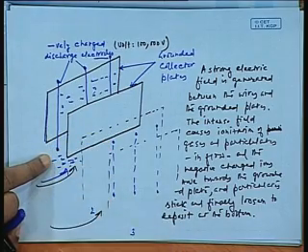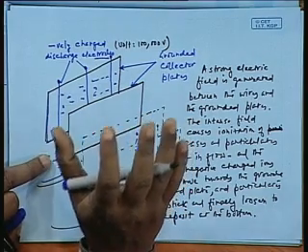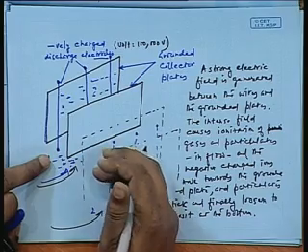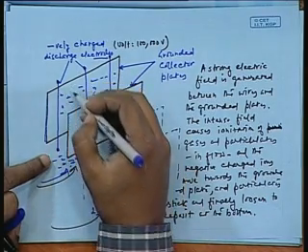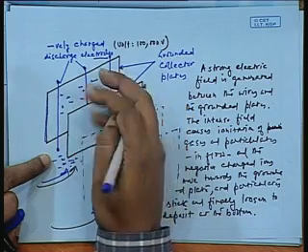They would collide with the grounded collector plates, and many of them would remain stuck to the plates. The gas would move upward, but the particulates would remain stuck to the grounded wall. Either by gravity they would settle at the bottom, or periodically the grounded plate has to be cleaned so as to get rid of all the particulates.